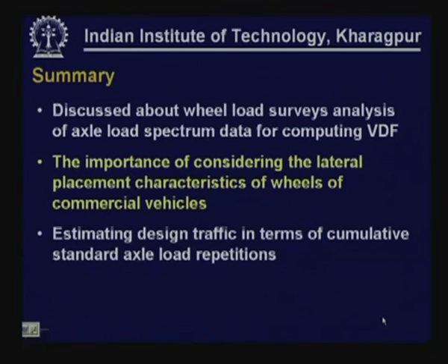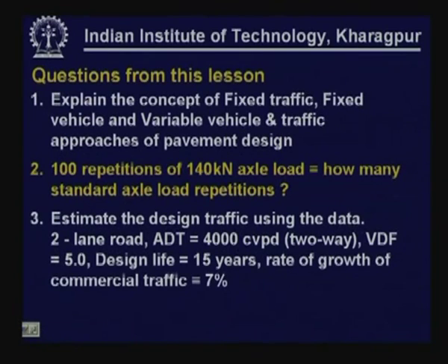We also discussed axle load surveys or wheel load surveys that can be conducted, and also the importance of considering lateral placement characteristics of wheel loads of commercial vehicles, and we have seen how, using all this information, the equivalent number of standard axle loads can be estimated for a design life period.